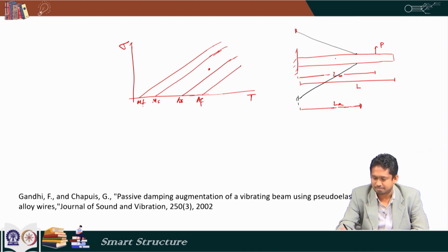So, when this beam tries to go up, this point moves up. If the beam goes up, in that case the length of the upper wire reduces, which means the tension is reducing here. So, it generates some amount of compression because of the upward movement.